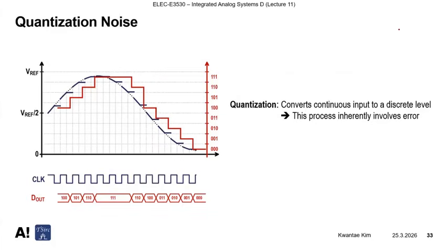By the way, I specifically drew the curve this way, so code 000 represents the middle point of each code range. So if you convert the digital value back to analog, then this may also touch 0 volt. So it will be going like this.